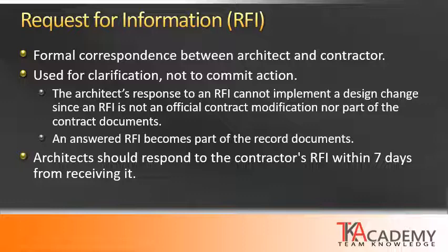Generally, architects should respond to the contractor's RFIs within 7 days from receiving it. Sometimes there are cases where an RFI response will take longer than that. If that is the case, the architect should notify the general contractor that it is going to take more time and when to expect a response for their RFI.